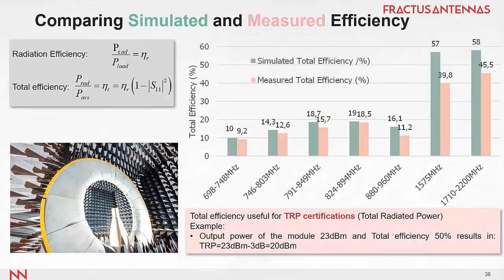And here we have the comparison between simulation and measured efficiency, in the lowest frequency region and in the highest frequency region, GPS, as well as all the high frequency region. You can see that the agreement is pretty good. In this case, we have less than 0.2, 0.3 dB of error, a little bit more in the high frequency, but nevertheless, it's a fully populated PCB, full of components, with a plastic cover, and the prediction is very good.